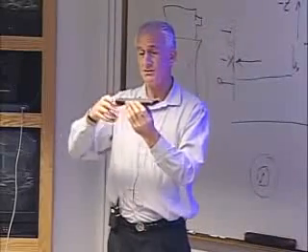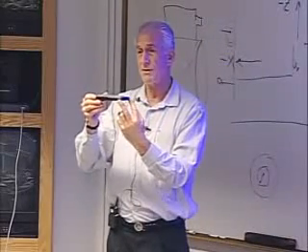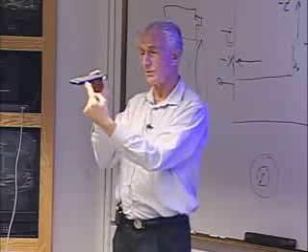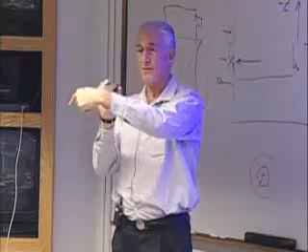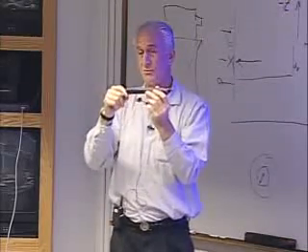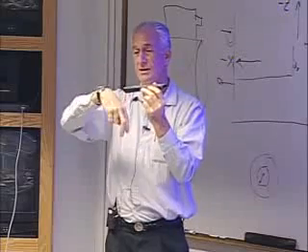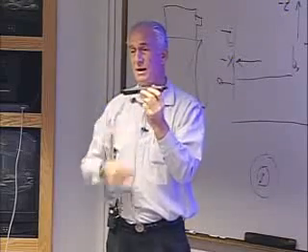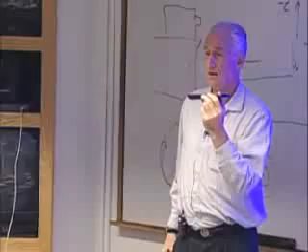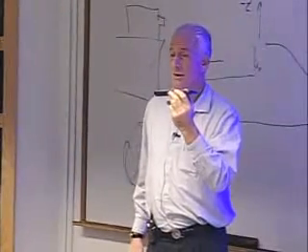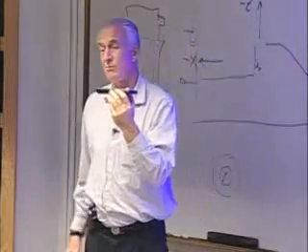So with the verniers, there's two verniers in the nose which are sort of canted down at about 45 degrees. And in the rear, there's two pointing straight down and two pointing straight out. So typically for a given maneuver, you'll fire only one or two.